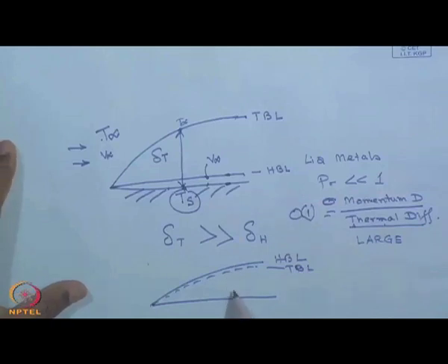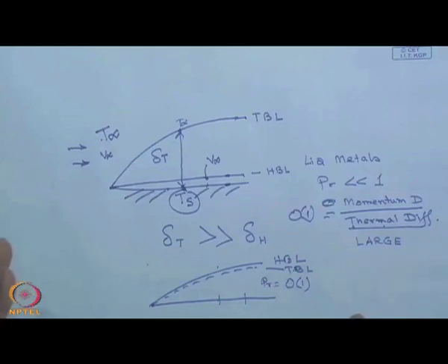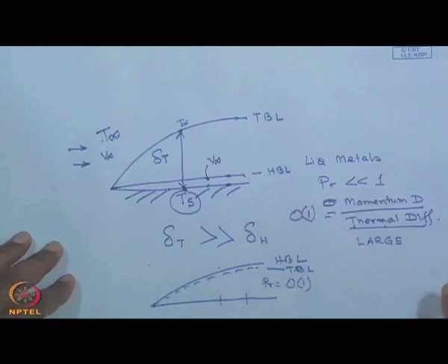That means, the boundary layer thicknesses at any axial position for these two cases would be almost equal if the value of Prandtl number is of the order of 1. So, the Prandtl number, Schmidt number, or similar such numbers carry information about the basic physics of the process, and not only do they allow us to compare between seemingly different transport processes, their values will also give us such important information.